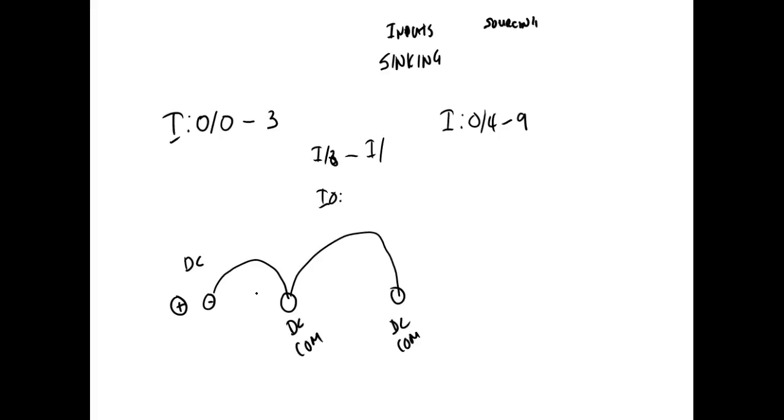Now, remember, if you use a syncing input, the device you hook up to it has to be a sourcing device. Y'all understand that? Yes or no? No. If I hook up, we're talking inputs right now. If I set my PLC up to sync, then the device I hook up to has to source. Y'all understand that?